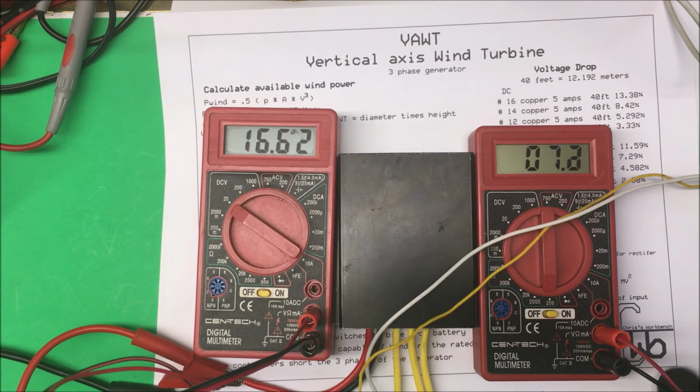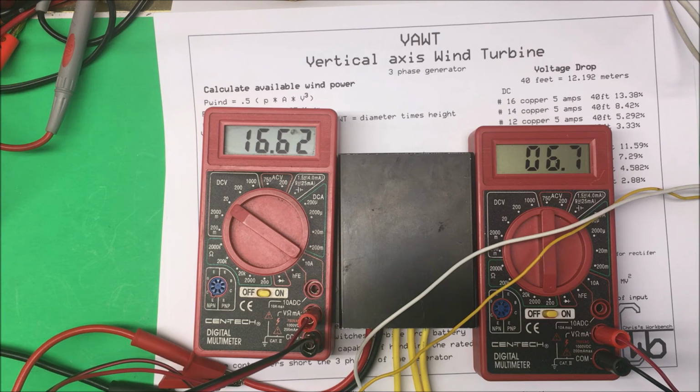And so that's the vertical wind turbine. We can only get about 800 milliamps out of it, not even an amp out of the thing. That's at 5 meters per second. Now at 10 or 15 meters per second, I can get a little bit more, and it takes about 15 meters per second to actually charge the battery. So that happens once or twice a year, so it's not worth it. But anyway, it's interesting to work with the thing, and you always learn something. So thank you.